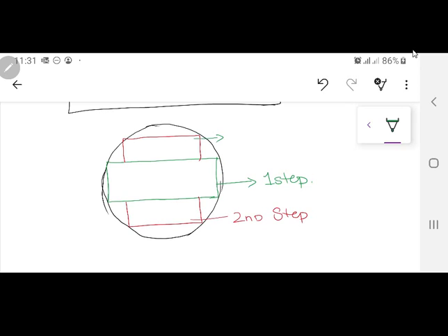Air gaps are less, the fill area of the circle is more. When you have a two-step core as compared to a one-step core, there are fewer vacant spaces. These areas are air, because when you design a transformer with a two-step core, you will not start winding directly on that core.